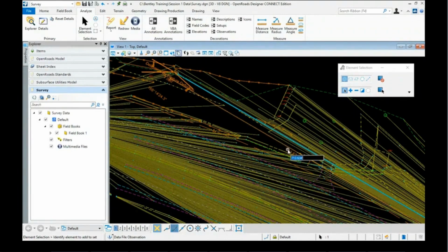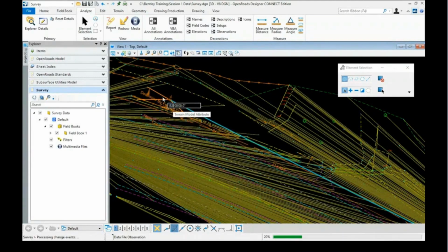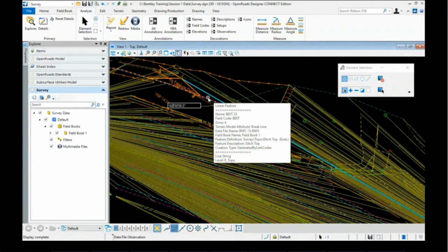So graphically, I can edit it. I can come in and I can click on that slope distance. I can make it 700, and we'll see the point pull in closer to the setup. I can come in and change the angle. If there's any reason where I actually have to change the observation data, I can make it 165, and I can see that point move down to 165. So I can edit anything graphically, and that's why we see these observation manipulators here. Also, so graphic is one method.